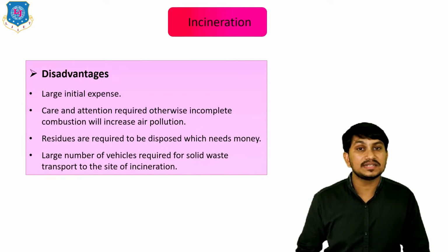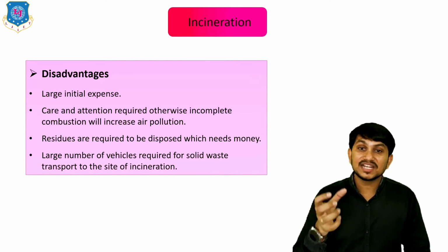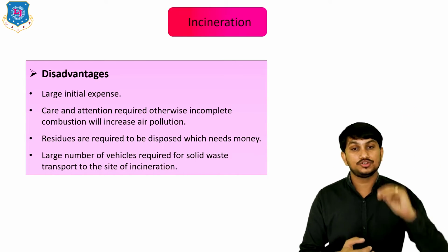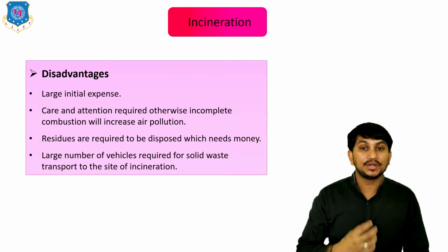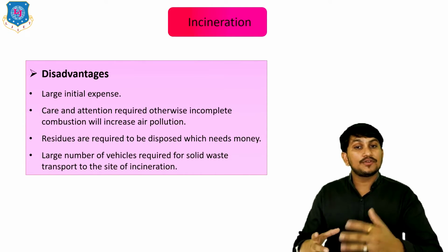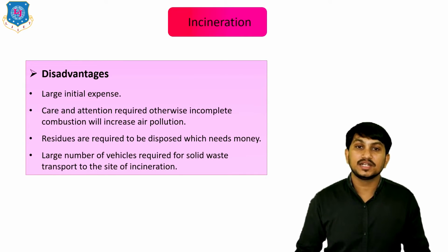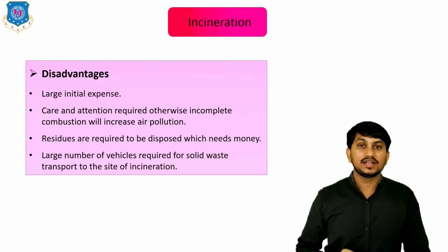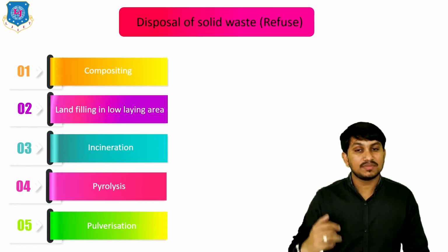Now let's see the disadvantages of the incineration method. It has a large initial expense. Care and attention are required, otherwise incomplete combustion will increase air pollution. Residues are required to be disposed, which needs money. A large number of vehicles are required for solid waste transport to the site of incineration. These are the four disadvantages of the incineration method. That's all about the incineration method.